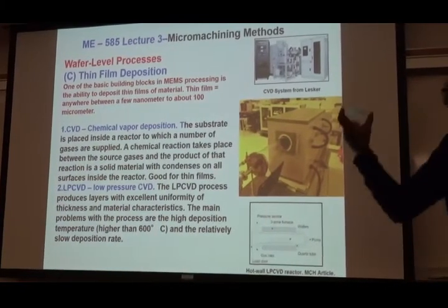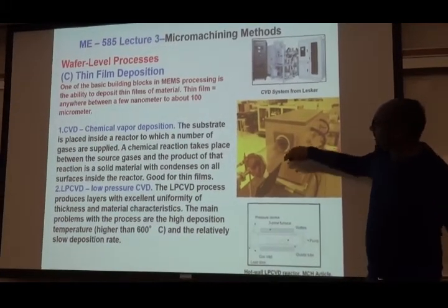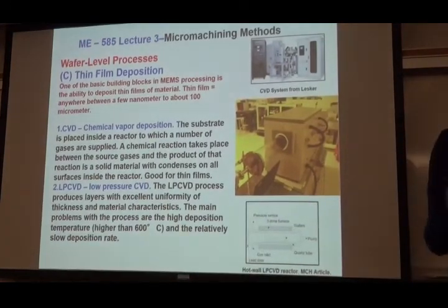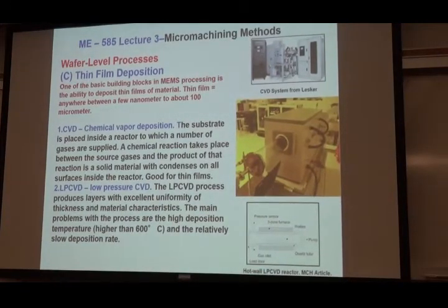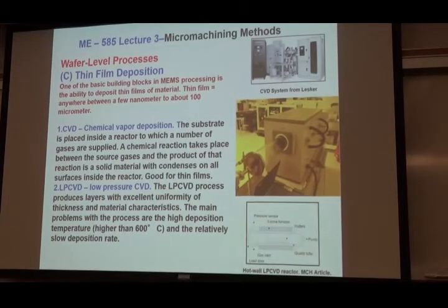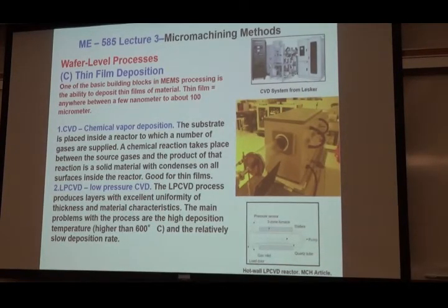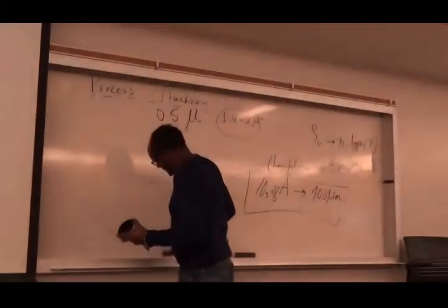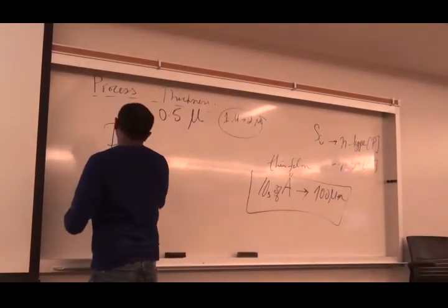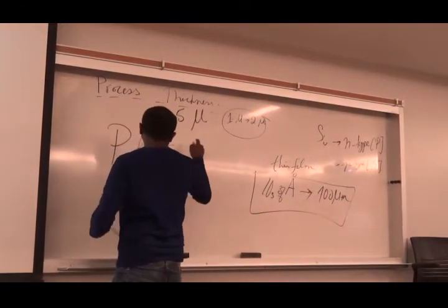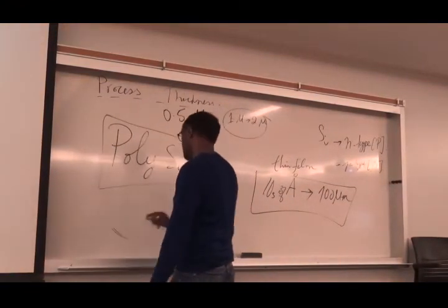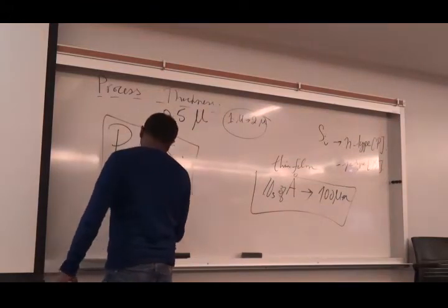So what you do is you take these wafers, you load them into a chamber, either this chamber or that chamber. You don't do one at a time. In a lab, yes, one. In an industrial scale, hundreds and hundreds of these wafers. You load them. And, for example, if I want to do it, this is very important, and it's going to form the basis of next week's lecture. Therefore, I need to put the name here. Poly-C-Si, also known as polysilicon.